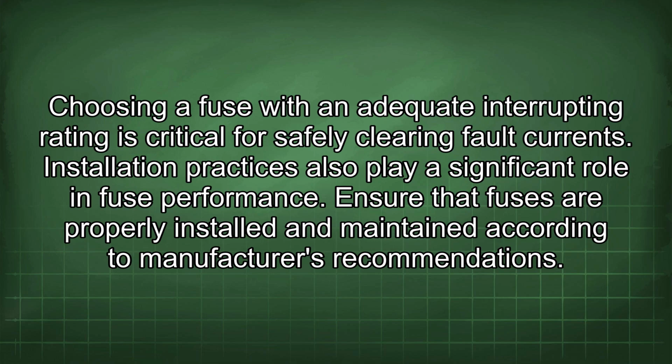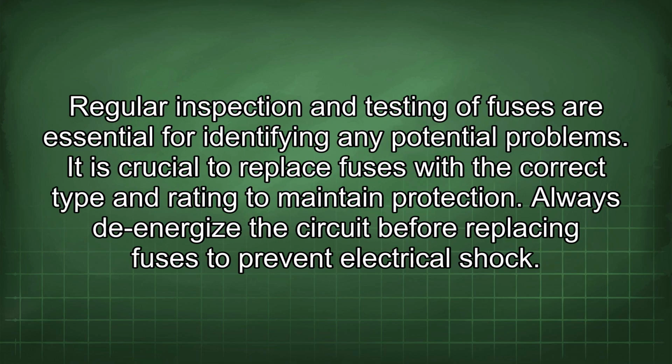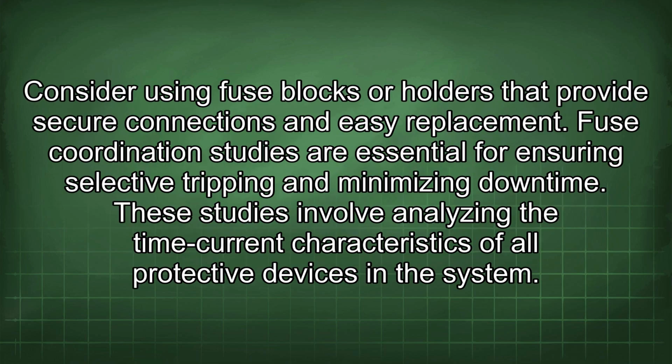Installation practices also play a significant role in fuse performance. Ensure that fuses are properly installed and maintained according to manufacturer's recommendations. Regular inspection and testing of fuses are essential for identifying any potential problems. It is crucial to replace fuses with the correct type and rating to maintain protection. Always de-energize the circuit before replacing fuses to prevent electrical shock. Consider using fuse blocks or holders that provide secure connections and easy replacement.